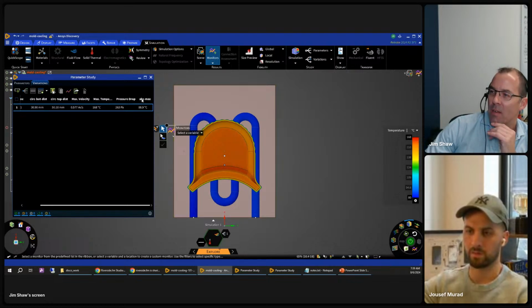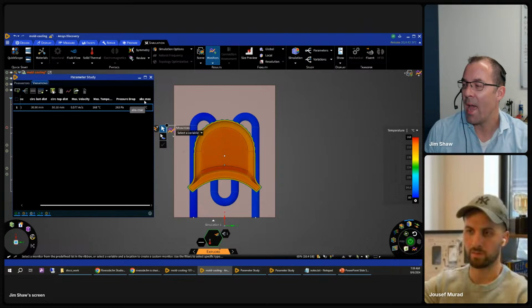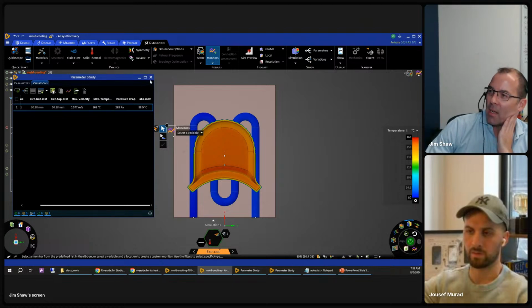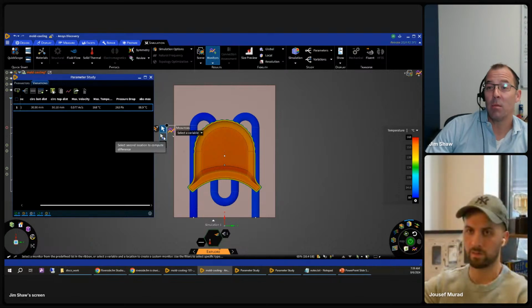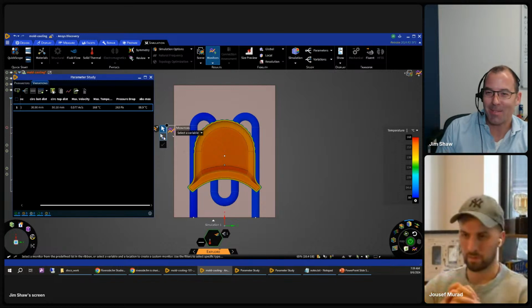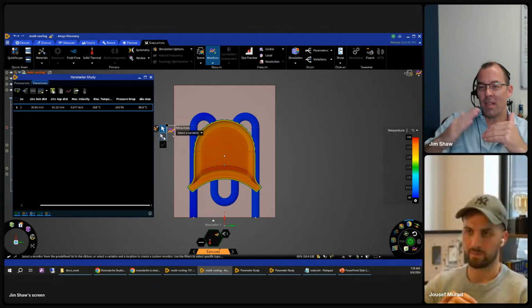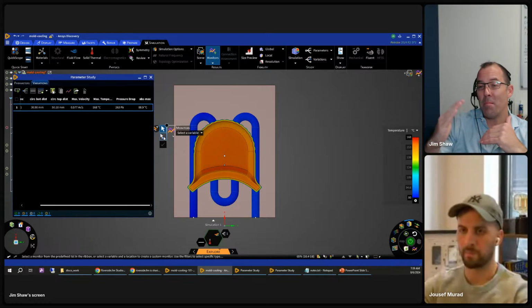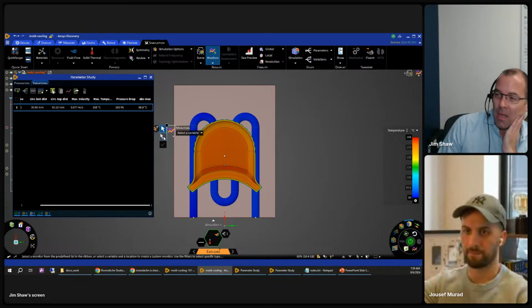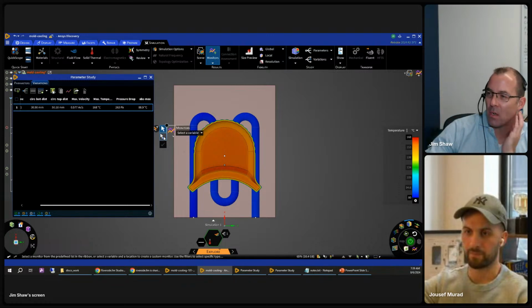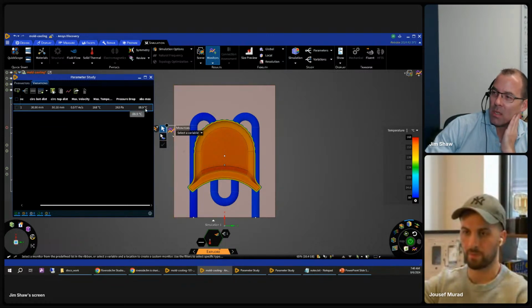I'm sorry if it's confusing. I realize that might seem like it's absolute max. That's actually the max temperature of the whole model. This is the max temperature of the plastic itself. So I haven't gone to the level of creating a difference, but right here, as you can see, I can reference a second location and compute the difference. So in a perfect world, Yusuf, if we were starting this in a few more hours and I could dial this model in a little bit better, we would say, what's the hot side of the mold? What's the cold side of the mold? And what's the difference? And we could optimize this model for minimizing the difference between the hot and the cold. I can always slide those around with my circuit. But right now, if you don't mind, we're just doing the maximum of that.